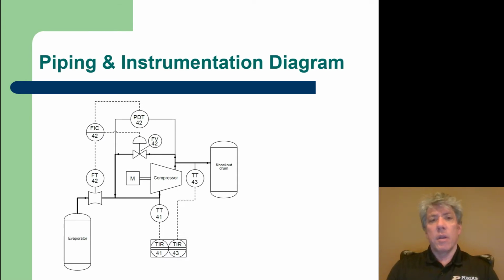Also, know one thing. Notice that piping and instrumentation diagrams have the short form of P&ID, and that's probably there to differentiate between a PID controller and a piping and instrumentation diagram. Both have P&ID in their names. So FIC, the flow indicating controller, number 42 there that you see, might be a PID controller. Notice it appears on a piping and instrumentation diagram, so a slight point of confusion there. Anyway, so we get to see more information here.